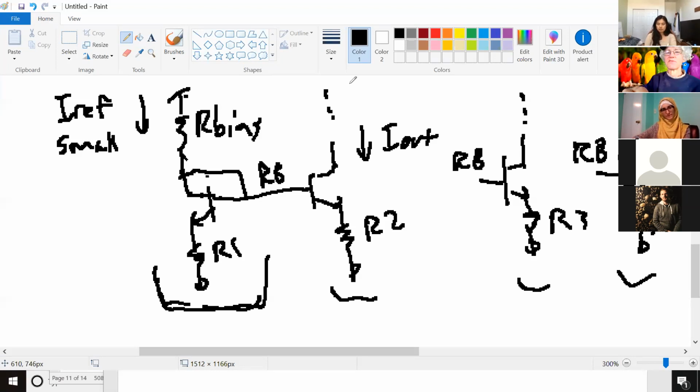So if these have to use power, then you've got to give them the current that they need to do their job. But why waste power over here if you don't need to? And to do that, you can put a smaller current through your circuit that's just generating RB, and then use as much current as you need through your actual amplifiers.